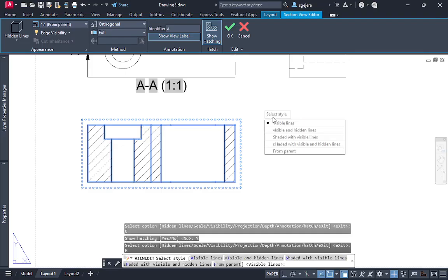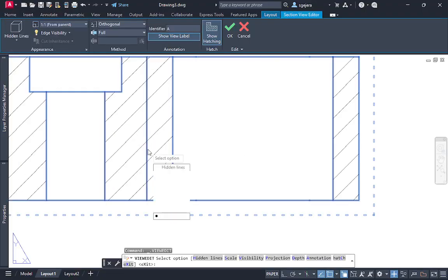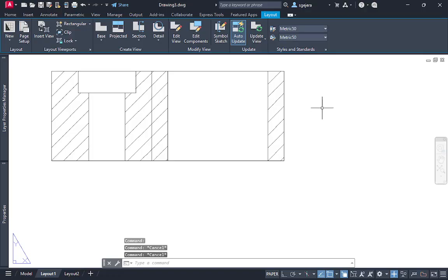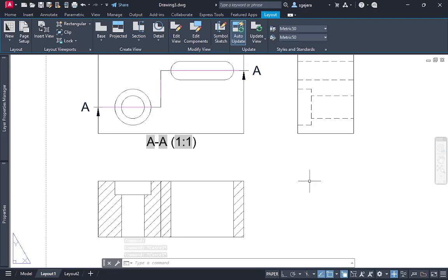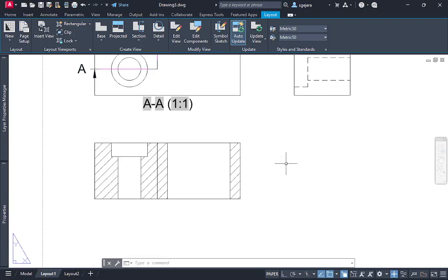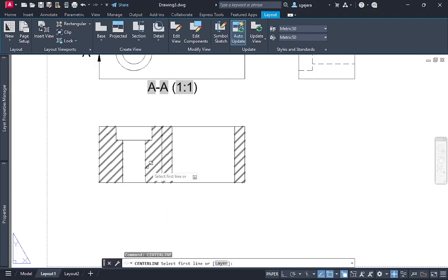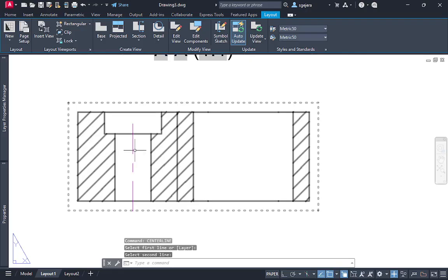Well, this is how AutoCAD presents it, no? In ES1, this line should not exist. This shouldn't exist, no? But since this is what AutoCAD produced, it shows the line where the bend occurred, so you can just use this as the final answer. But before this, we need center lines. So we create center lines for this one and this one. So, here it is. And we create another center line for this one and this one.